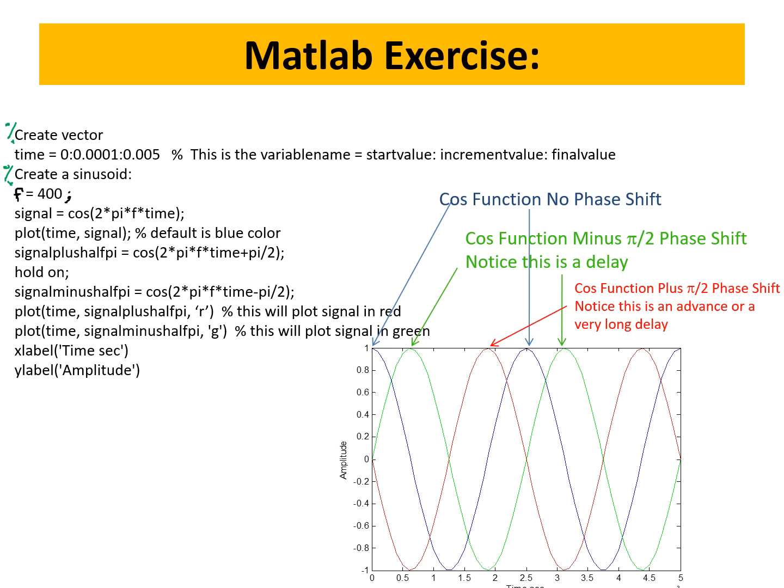So let's go into what we are looking at. You defined a time vector, and the time vector is your x-axis. Here you start from 0 and you end at 0.005, with each increment being 0.0001. Very small increments, which means we have a lot of samples in between. That's how you define time: starting value, colon, step, colon, and then the end time.